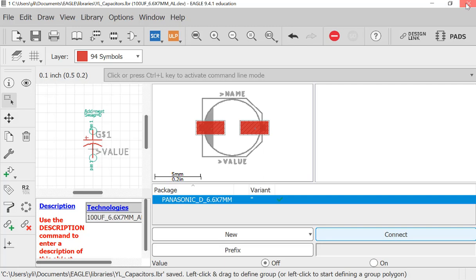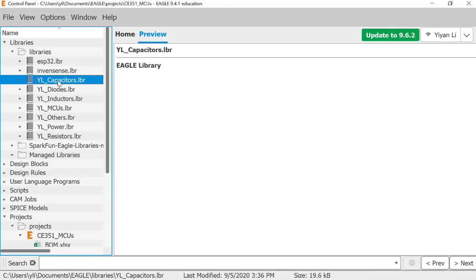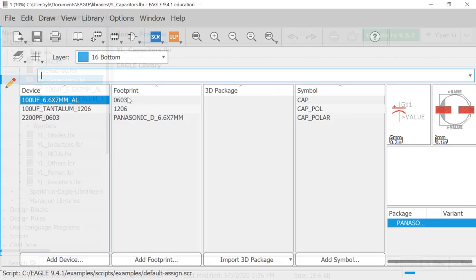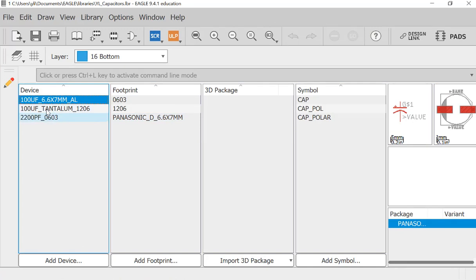And let's go forward. If you go to the package, let's do a double check really quickly. So you can see here, that's the capacitor we just made. Okay, here's the symbol, here's the package. So that's how you make it quickly. I'm going to show you how to draw it for one of the 4 capacitors. But now, as long as we can just directly borrow the footprint or the symbol from the library, let's just use that one, so it makes things quicker.